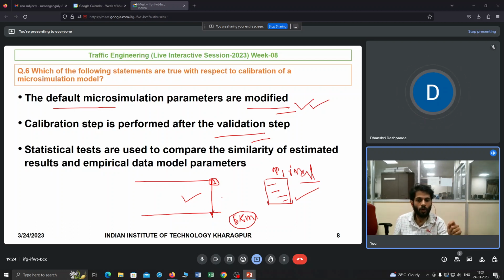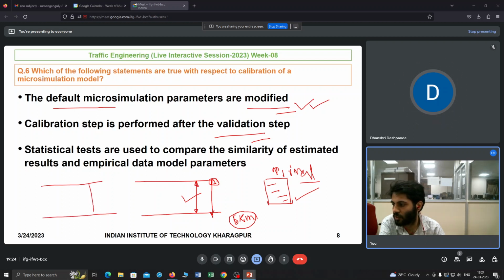Even in off-peak, where the traffic volumes are less than peak, you want to calibrate the model. You do not want your simulation to go haywire, right? Another point is, suppose for this road geometry your parameters are sufficient. Suppose you have some 2-3 stretches in the same city maybe, so you want to achieve a global calibration kind of thing.